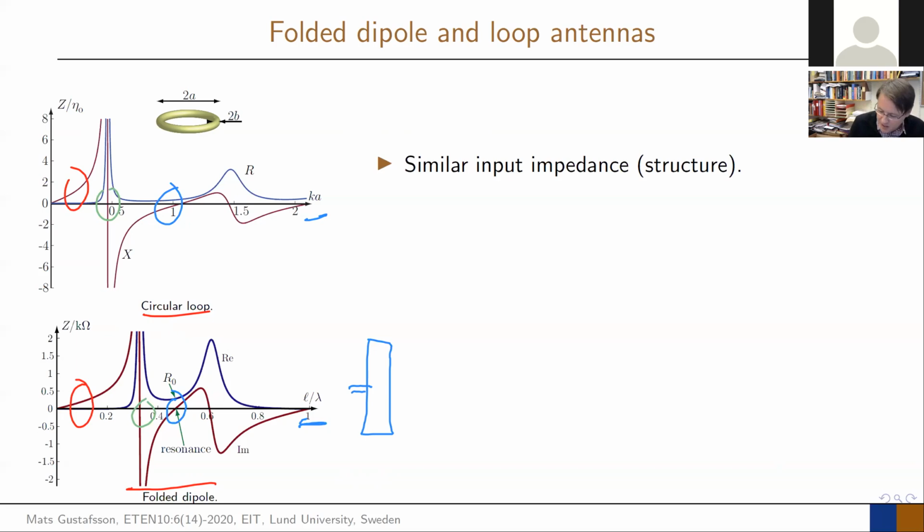And then the distance between the radiating dipoles, this d, is of course much, much less than the d of these ones. Because in that one, these were on a circle that goes around here, which has a much larger separation between the dipoles. And that means that the folded dipole radiates more like one dipole pattern. But in the loop, we need to really separate them and see the phase difference between those two, and we get a different radiation pattern.